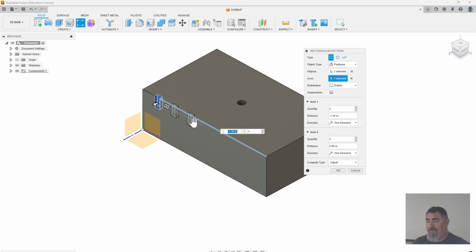That's maybe okay if you want to have like a 3-inch area and you want to fill it equally within that space, and you don't really care about the spacing in between each individual thing. You can do that, but usually you want to change that to spacing, so we can define the spacing between each one. You can use this little handle here to expand. You can pull one way to add more instances, pull another way to reduce the number of instances. You can see the spacing between them stays the same, it just adds more or less.